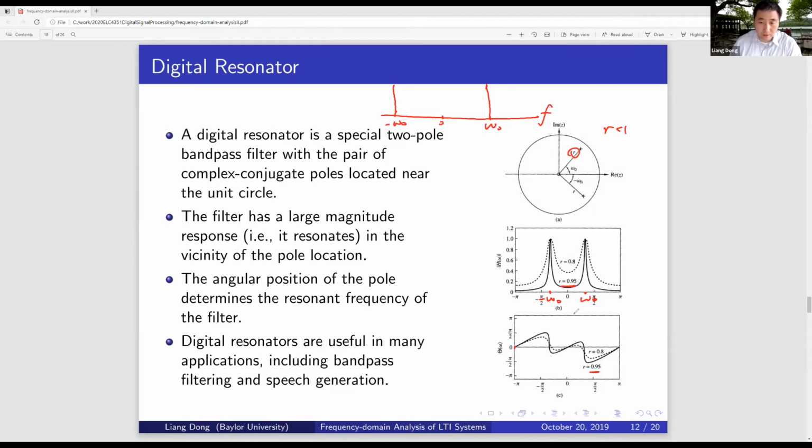As we discussed before, we can implement that by placing the poles. If you have a pole, it means you have something in the denominator, right? Its pole really comes from the A(z) in the denominator. That gives you the poles. If you have some concrete, non-zero poles on the Z-plane, then you will have this denominator, and therefore we have a feedback, right? This is Y over X. So you have feedback. Therefore, this filter is most likely an infinite impulse response filter.